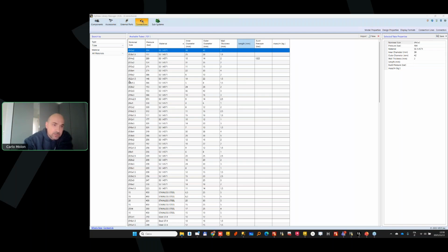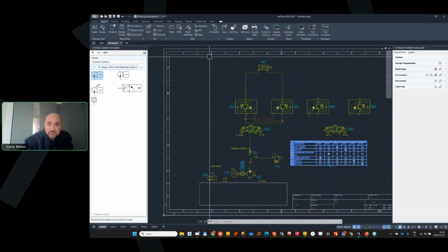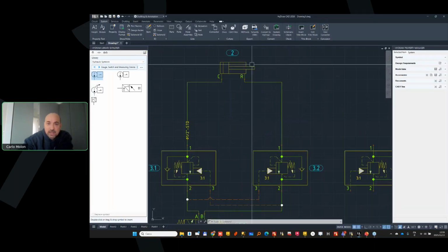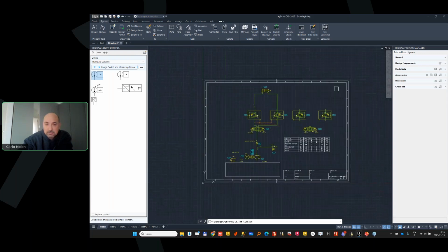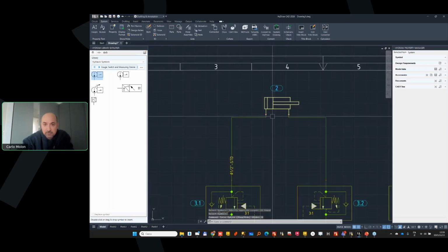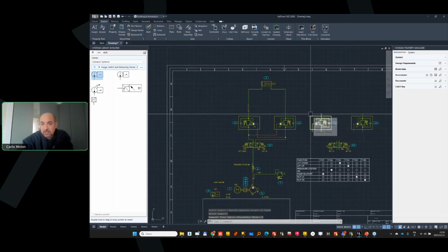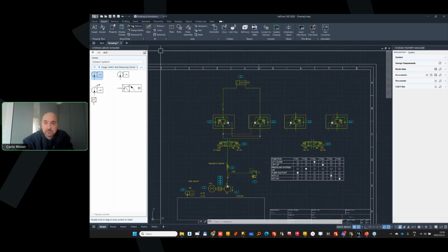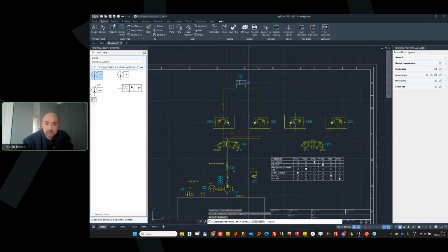There is another question. Some symbol I prefer no label on ports. Yes, that's tricky. So the request is, how can I hide the symbol port without deleting? This command has been there for many years. Port names, you can select the symbol that you need, maybe all these ones, enter and select hide. This command will hide the port names. So you don't need to delete, you don't need to edit, and it makes sense not to delete or edit, just port names, select all and show.